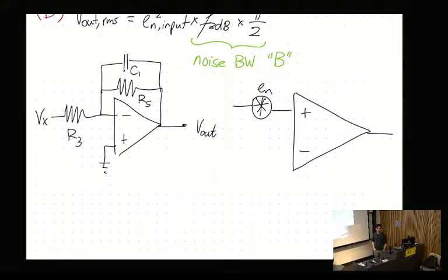So if I don't know where a pole location is, what do I derive? Transfer function, right? Again, even if it's the longest method, I know it's going to work. So I just derive a transfer function. And this one's really simple because what type of amplifier does it look like? If I just consider this whole thing as Z, then I have an impedance in the feedback loop and an impedance at the source. So it's just an inverting amplifier.